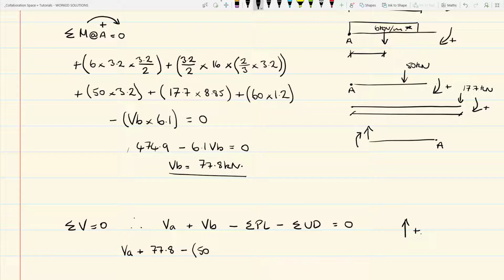We also have the vertical component of the inclined point load, so that's 17.7. Those two are both acting down, so they are negative. The point load to the left-hand end of the cantilever is acting vertically up, so that is positive. Going back to our original assumption, we assumed that loads acting up are positive, so it's plus 60.